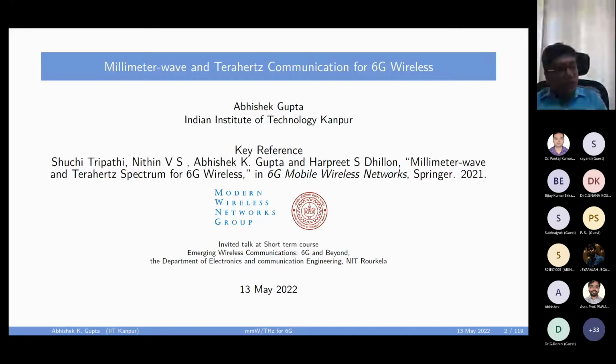And this means if you think there are 20, 30,000 people in that stadium, that creates a huge data demand in a very small area. They are mostly fixed because these users are sitting, so they are not moving that much. So in these stadiums, you can deploy millimeter wave base stations very closely, where they can provide very good coverage, coordinated beams to these networks. So that is one application where the blockage does not really play a role because everything is close by and you're talking about a seated setting.